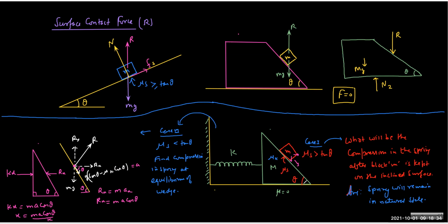Now, if you draw the FBD of the block only, it will have forces Rx, mg, and Ry. See, the benefit I'm getting here without drawing the normal and friction is that I have fewer variables.